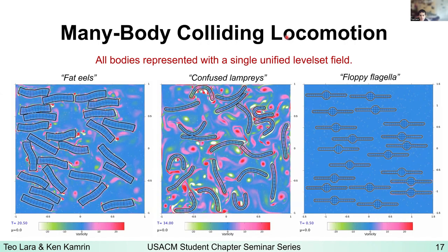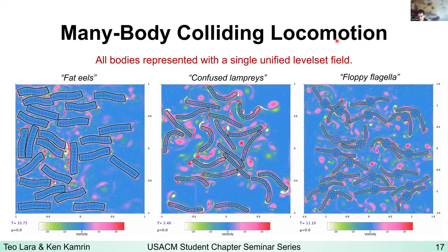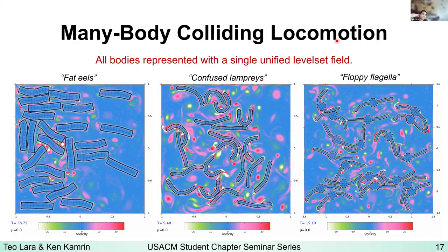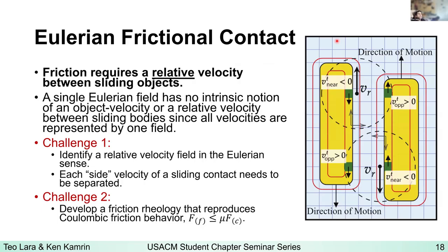Now, a more recent extension of this contact work has to do with frictional contact. This is something we started thinking about last year, in that the contact between two bodies will generally not only have a normal component keeping the bodies from touching each other, but also a tangential component, right, preventing sliding and causing the bodies to stick together. And that is called friction. So can we add friction to our contact model for this reference map technique?